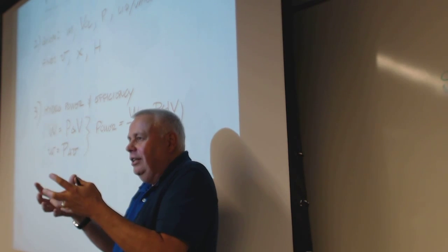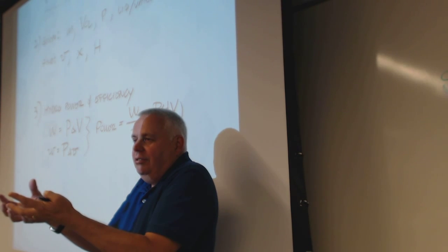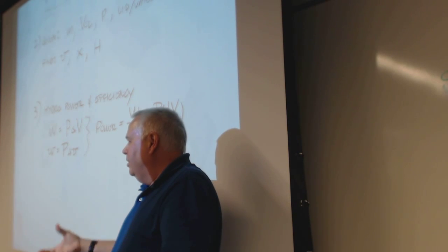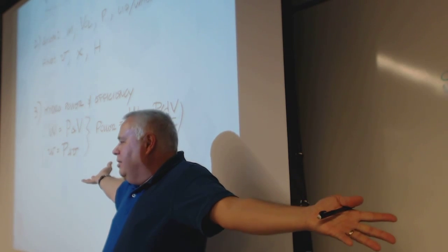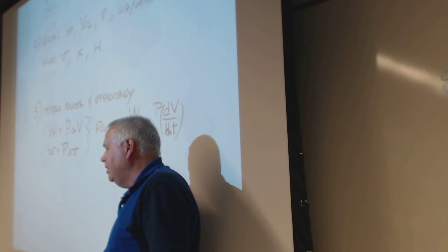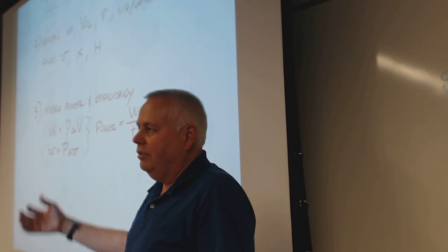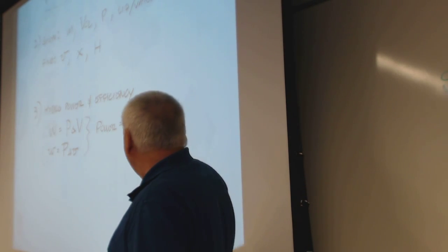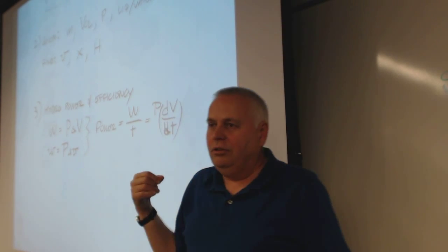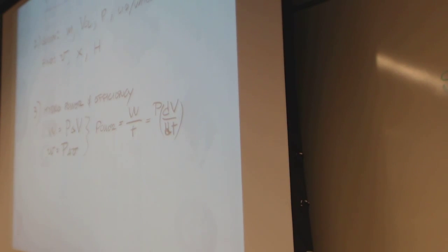There's no kinetic energy left, so it just stays at the bottom of the turbine, which blocks the rest of it. So you can't use all the energy from the water, because it can't literally get out of its own way. So you have to leave some energy for it to leave. So it's never going to be 100% efficient in converting the potential energy. And pressure is potential energy, basically. It actually has units of kilojoules per cubic meter, if you think about it.